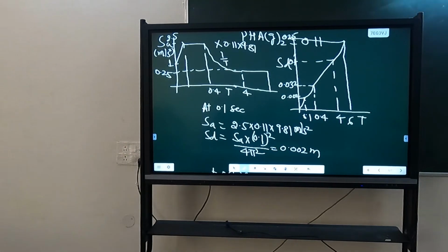Mean doesn't mean that I have hundreds of sources, so I will take the mean. Otherwise, I will go on increasing the area. In place of 300 kilometer, I take a radius of 1000 kilometer. So many small earthquakes will come whose PGA will be very small there. So the mean will keep reducing. So mean doesn't mean that we have to take the average of all the sources. It is the mean PGA obtained from the governing source. Okay, any other doubt?